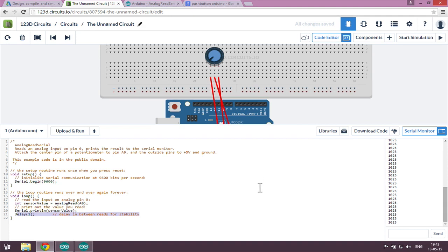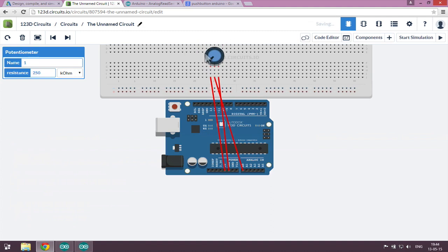It's needed. So this is how you can put in an analog signal and just read the value of this analog signal. So you can now use this knowledge inside your project. This script you can just use, and if you start the simulation, you can build something that, depending upon this knob here, something else changes as well. For instance, a motor will be spinning faster or slower. You can do that.